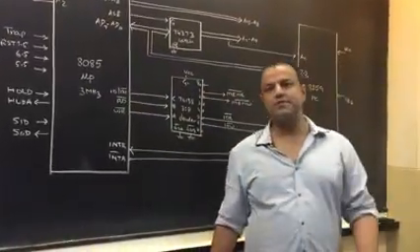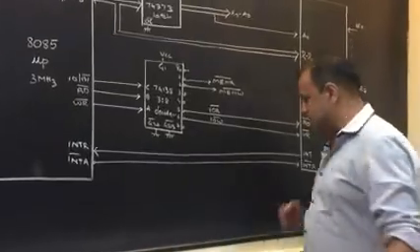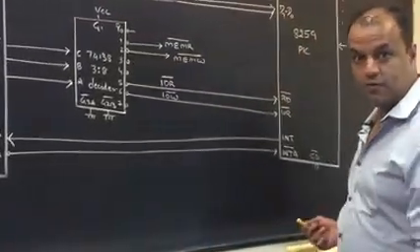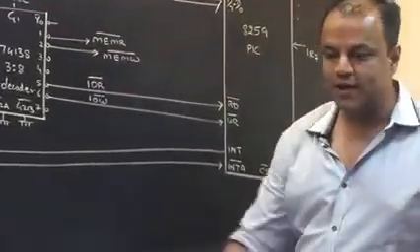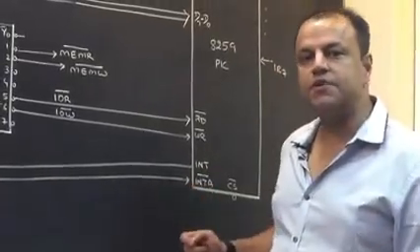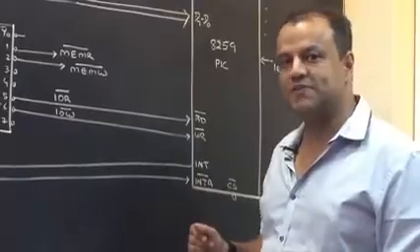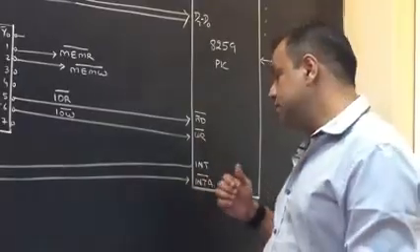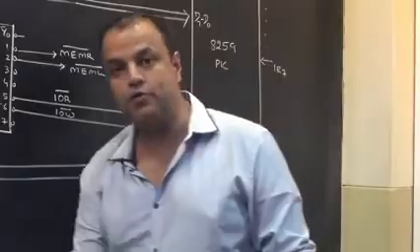So students say, sir, if it needs a 0, why bother? Just ground it. Ground gives you a 0. So ground it, the chip will be selected. No, we can't do that. If that was the case, this signal would have never been there. See, when you ground it, you're giving a permanent 0. That means you're saying this chip will always be selected. Now that should not happen. This chip should be selected only when it's meant to be selected.